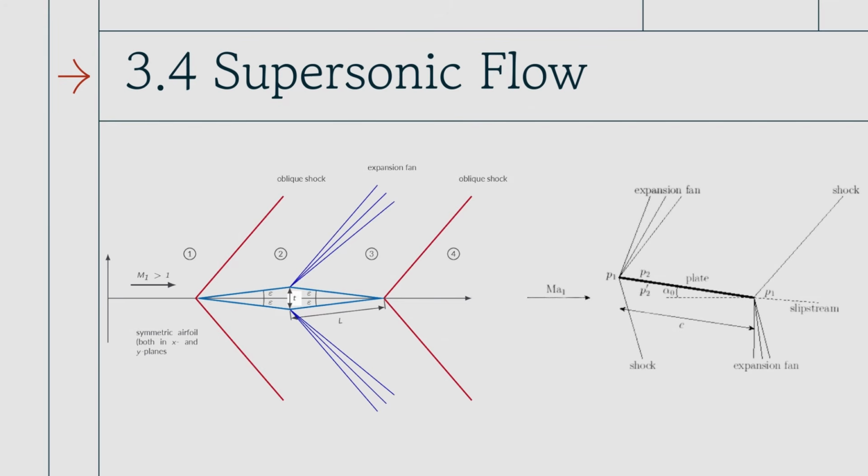At the end of the day, expansion fans and shockwaves are just pressure gradients. They're regions of high or low pressure, but that can affect the forces on your canards. Do you want your vehicle shape to be such that you have an expansion fan? Or no? Expansion fans are not inherently bad. They occur naturally with shockwaves, but they are a little bit different.